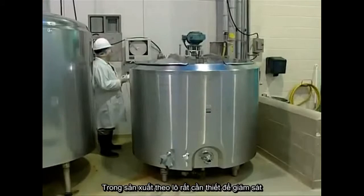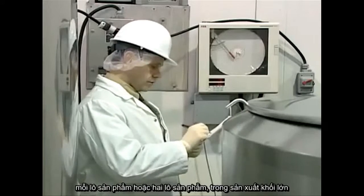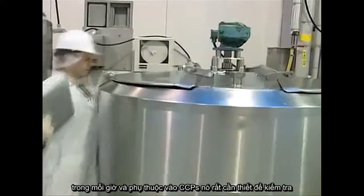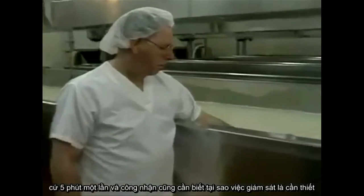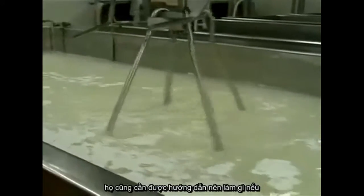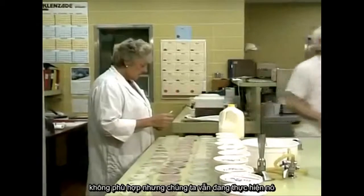For batch processes, it may be necessary to monitor every batch of product or second batch in large volume production, where thousands of kilograms of products are produced in an hour, and depending on the CCP, it may be necessary to monitor every 5 minutes. Employees need to know why monitoring is necessary. They also need to be trained to conduct the testing, and they need to be shown what action to take if there is a deviation. Or in other words, when a critical limit has not been met.